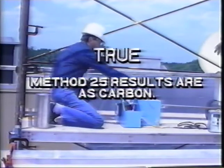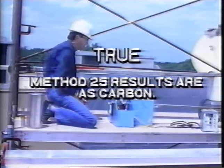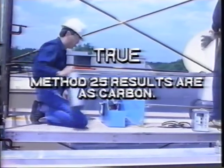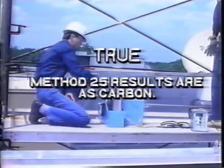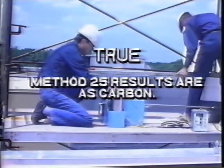4. Method 25 results must be divided by 6 to express the concentration as hexane. True. Method 25 results are as carbon, and hexane has 6 carbons. Therefore, Method 25 results must be divided by 6 for the concentration to be expressed as hexane.